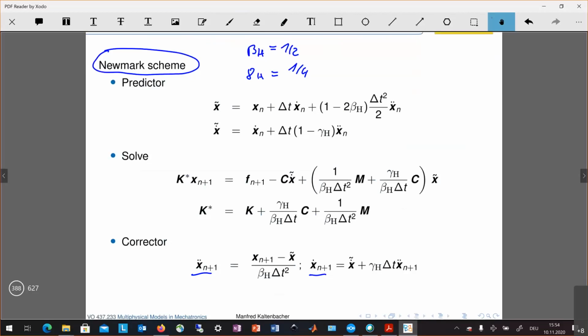Anyway, the mechanical displacement is a vector. It has three components, the x, y, and z component, and therefore also our test function is a vectorial test function, and we have seen how you can get out by the dot product also three equations, because we have three unknowns, x, y, and z in the continuous setting, and the discretization is similar as we have discussed for the scalar partial differential equation.